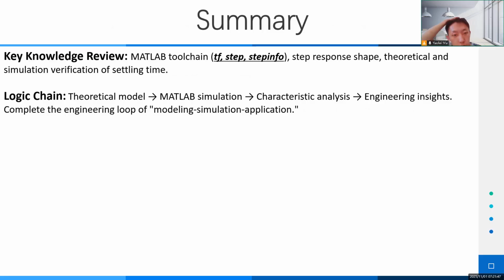Let's wrap up this part of the homework. First, we review key knowledge. MATLAB tools: using TF to build the model, step to plot the response, and stepinfo to get settling time. What a step response curve looks like and what it tells us. Checking if simulation results match theoretical calculations like settling time.